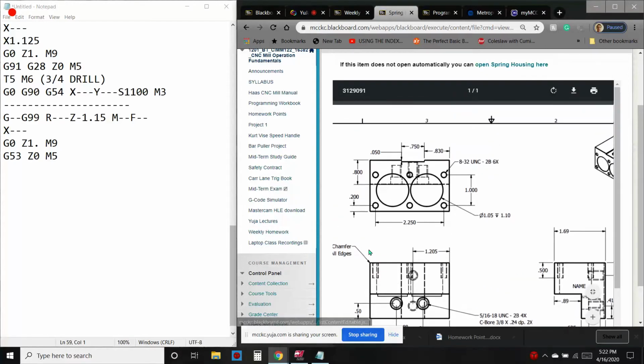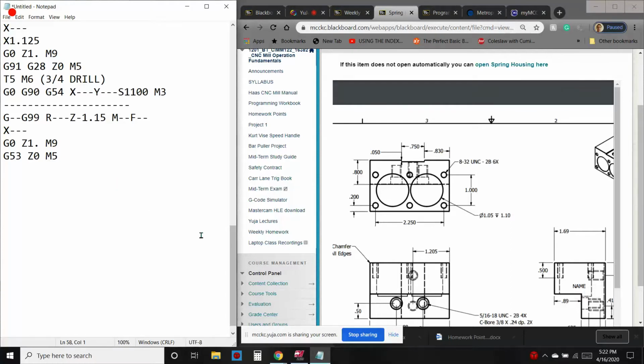So then we go through it again with a finish mill and clean it up in one pass. So since we don't have to find 3/4 inch end mills, we'll just go ahead and program a rough pass and then a finish pass, maybe just one circle. So cutting circles is pretty fun and it's really pretty easy also.